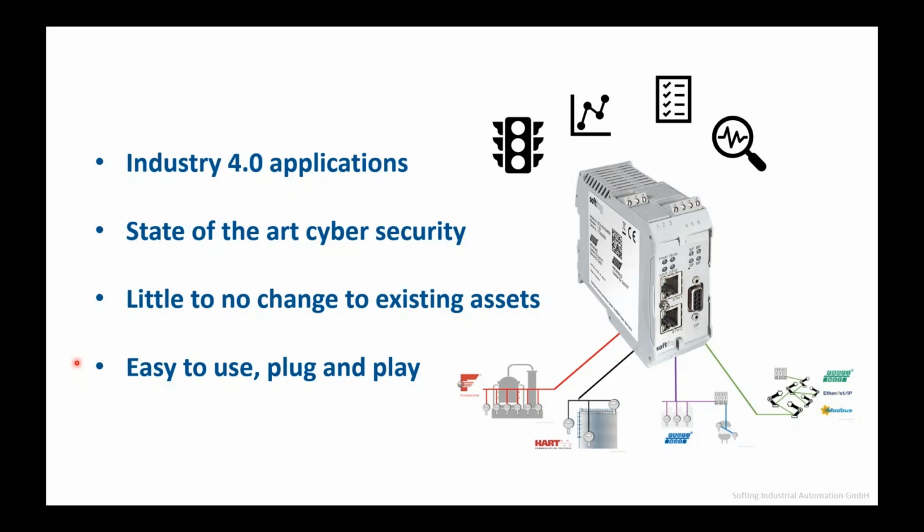This is no problem due to no power-over-bus capabilities in those protocols. But if you talk about fieldbus, Profibus PA, Foundation Fieldbus, and so on, our gateways do not provide power to those systems. You can use existing power supplies on the other hand, so you don't have to exchange those. We do not interfere with power supplies of different vendors.